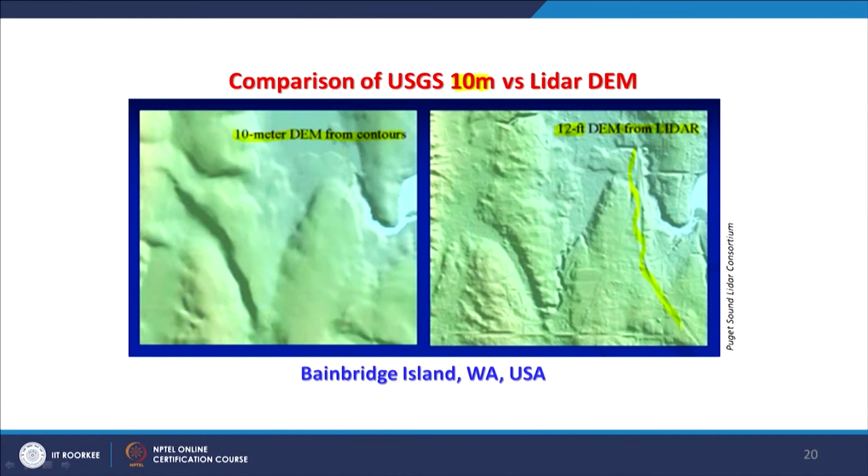That is why you are seeing some human-made structures even in this bare LiDAR DEM. So, that may be one of the problems associated with LiDAR DEM. Otherwise, it can produce a very high resolution digital elevation model without any big problems.